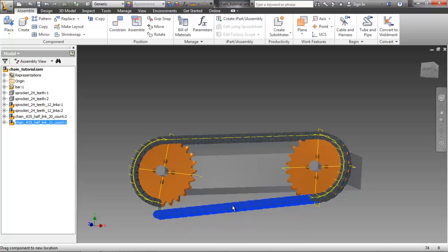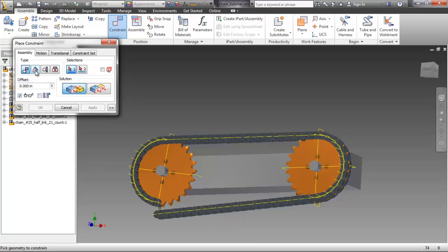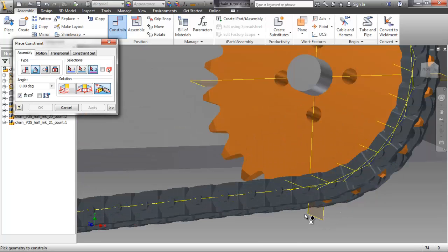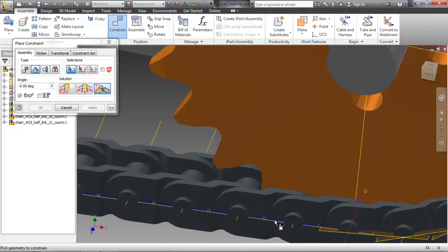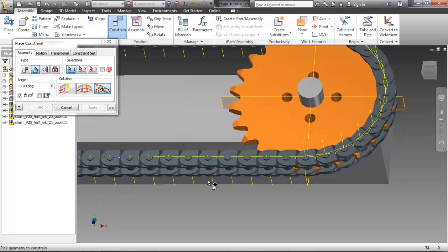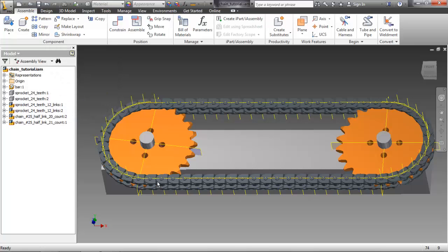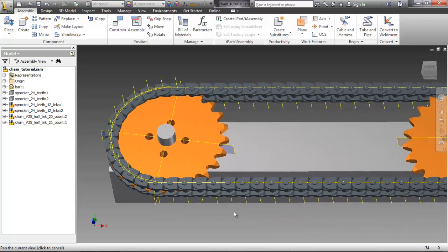And the bottom chain segment can still rotate freely, so you need an angle constraint. So select 3 and select the axis connecting the curved chain segment with the straight chain segment, and select the straight chain segment workplane. And now grab the bottom of the bar. By adding the extra link, you can see how it lines up with the curved chain segment.